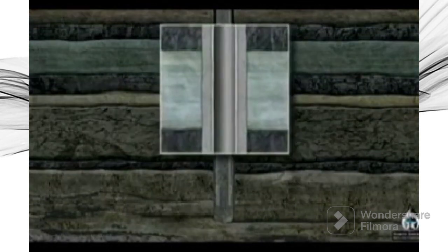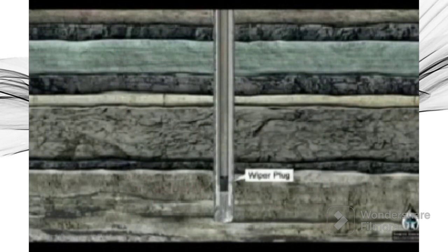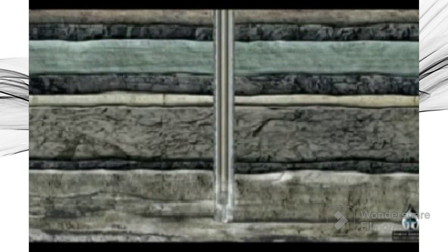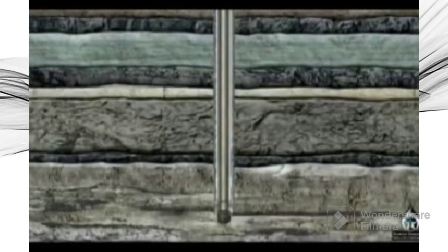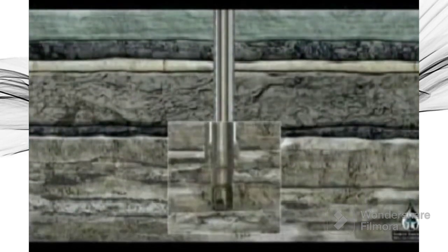Once the casing cement has set, drilling of the intermediate section of the hole continues by drilling through the wiper plug, shoe and cement at the bottom of the wellbore and onto the targeted zone. Throughout the drilling, a mixture called mud is pumped down into the well through the drill pipe. The mud serves to keep the bit cool. It carries the cuttings to the surface and provides hydrostatic pressure, inhibiting formation fluid from entering the wellbore. Now, the drilling approaches the depth of the target zone.